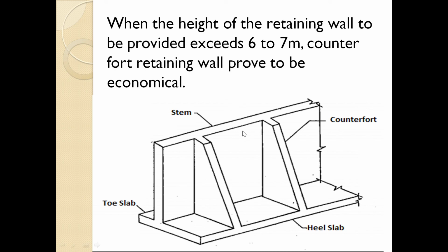The counterforts are provided at certain intervals. Actually, in this diagram, the counterforts are provided at certain intervals which will support the heel slab and stem. So stem and heel slab act as a continuous slab, but toe slab acts as a cantilever.